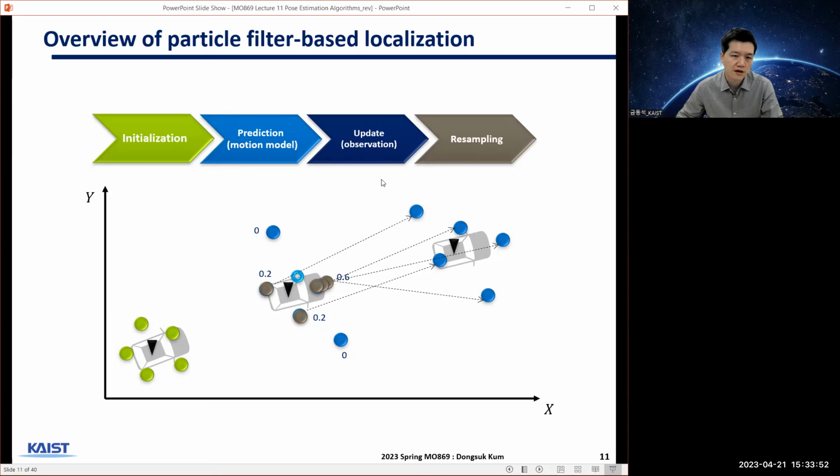So we have measurements again now, at k+1. We can apply the measurements, update with the measurement. So we can remove things that are far apart from the measurements, and put more weights on the particles that are closer to the measurements. Okay. So that way we can keep this distribution bounded and small over time.